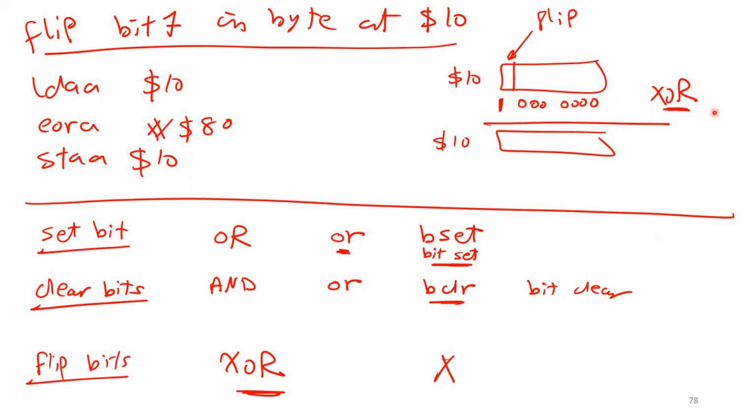So here, do you have an XOR instruction to do XOR for a byte in memory and this immediate value, and to store the result in this one? No, we don't. We don't have instructions that can work on XOR directly on memory. So number one, guys, I have to load. I have to read a byte from memory and put it in A, right? And then I'm going to work on A. Okay. So now I did the XOR, but the result is in A. So I have to return it back to memory. Okay, guys. Any questions?